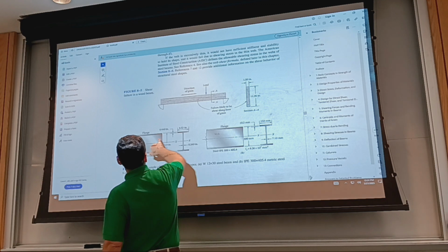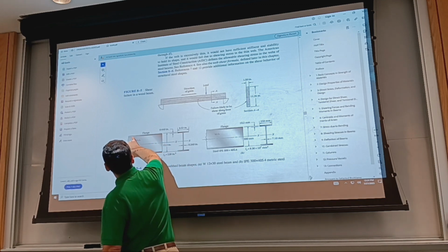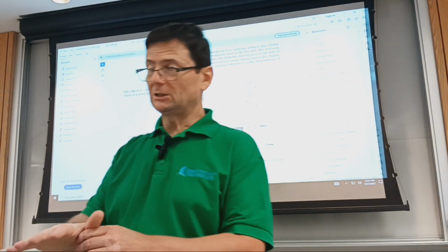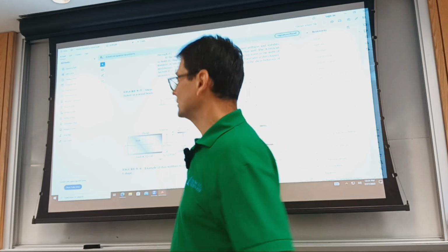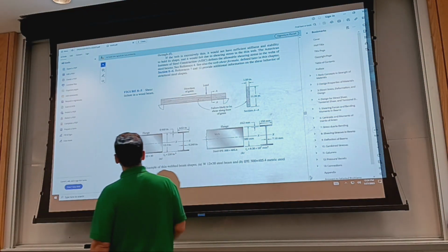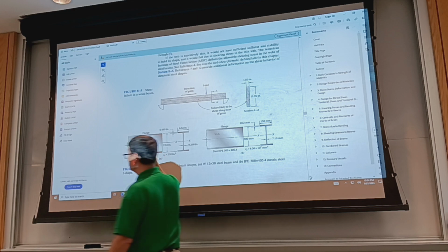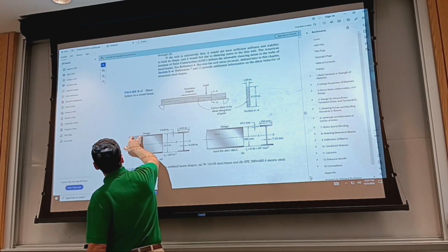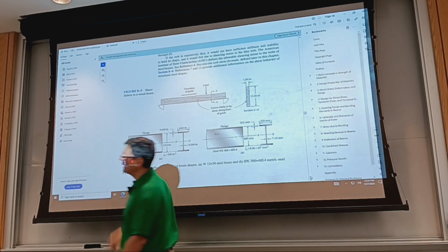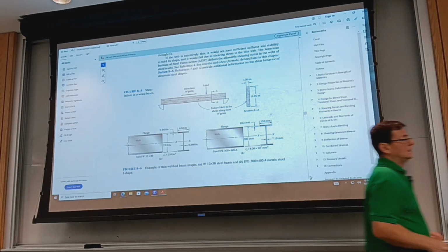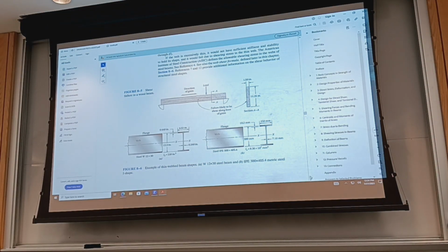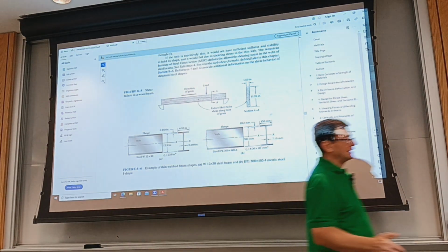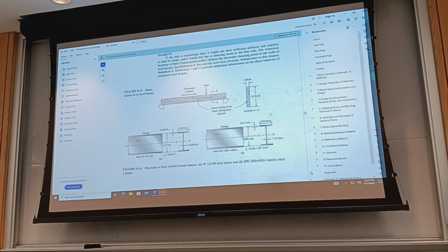Well, we can do analysis and calculate based on the shear force ability. How much shear force can the fastener, the nail, or the wood screw hold, or it could be the glue if you're gluing them together? What's the maximum spacing they have to be? There should be a maximum required spacing, and you go less than that. So yeah, designing or calculating fabricated beams.